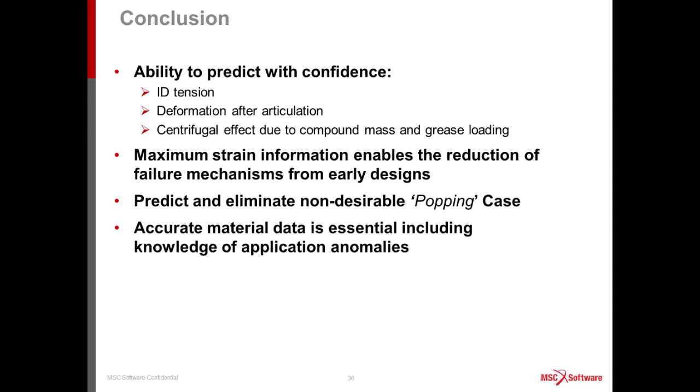It allows us to predict and eliminate the non-desirable popping case, which is not something you want on a CV boot. But again, accurate material data is essential, be it at the right state of stress and strain or temperature. And you also need to have a knowledge of the application anomalies that you see with certain types of joints, as that can cause significant issues.